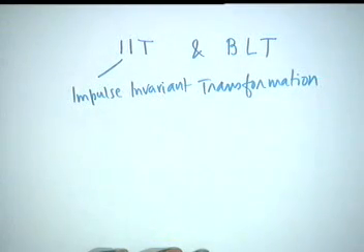If the distortion can be contained within a reasonable limit, then it does the job. Most of the IIR filters, for biomedical signal processing for example, people do not want to go into the complication of bilinear transformation. They simply use impulse invariant transformation, and if it works, for an engineer, that is good enough. So people still use IIT. Mitra's second edition, for example, does not discuss IIT at all, he only uses bilinear transformation. That is one reason why I am asking you to take careful notes.